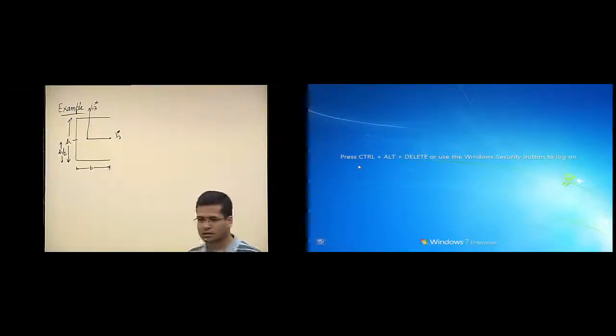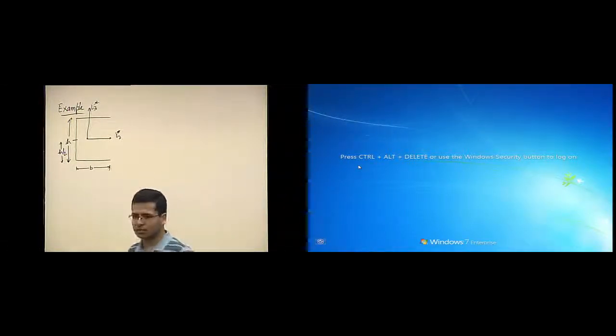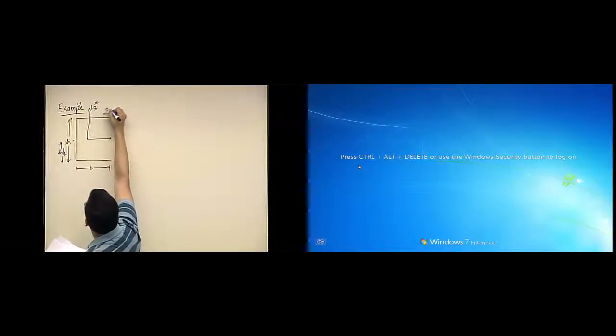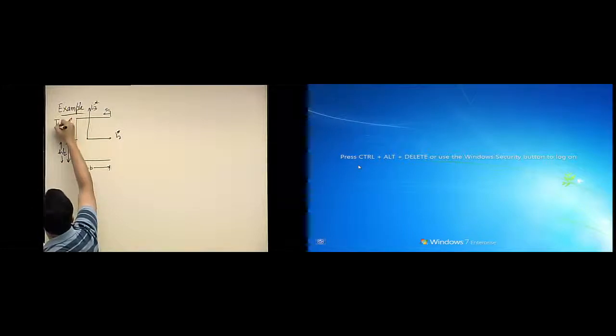In any thin wall beam problem, if I have multiple segments such as this C section, I have the freedom to choose my S coordinate directions. So I can choose S1 in this direction, S2 for segment 2 in this direction, and for the third I can choose my S3 starting from this open end.